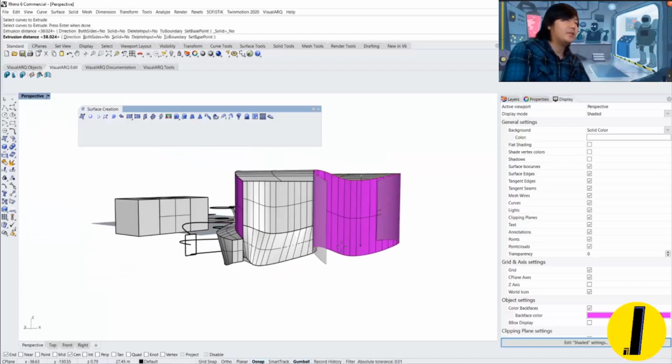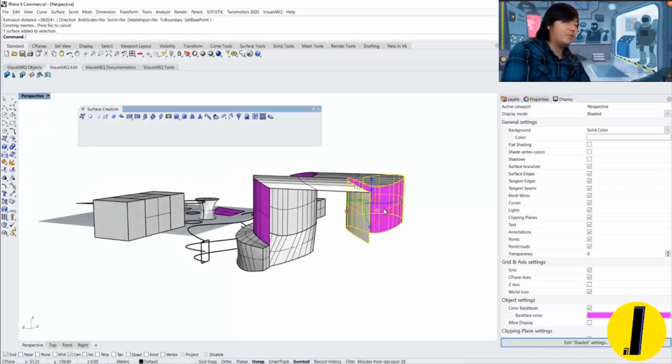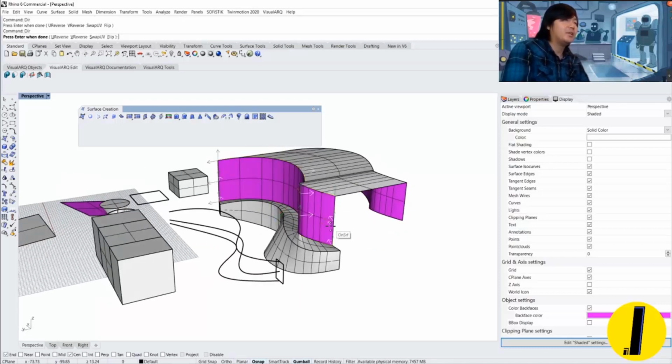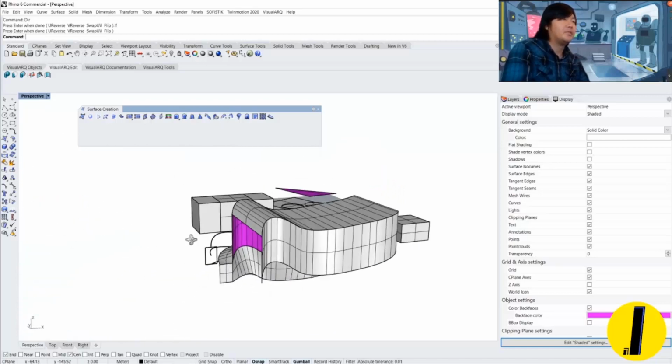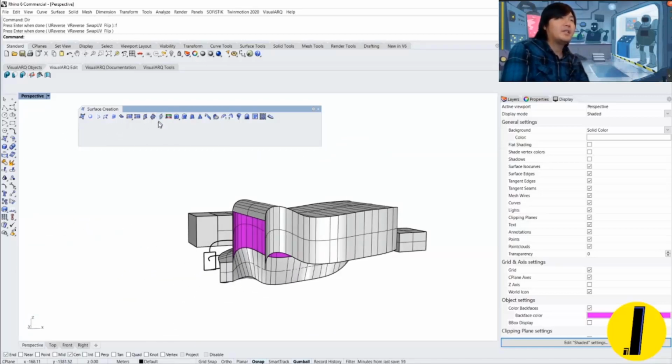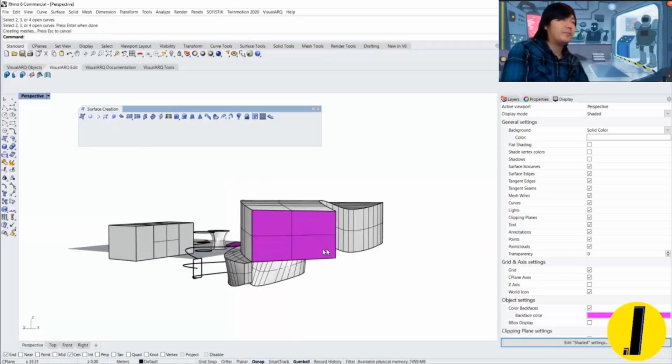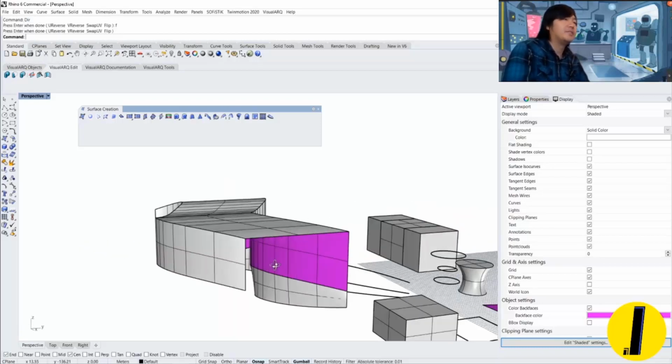So it's a really nice tool. You can always flip the direction. Type dir, and you can flip the direction of the surface, and it goes the same here. Flip. So we have this sort of geometry, and let's keep repeating. I can use curve from 2 or 3 curve to close this part, and I'm going to type dir, flip, and we have this surface.